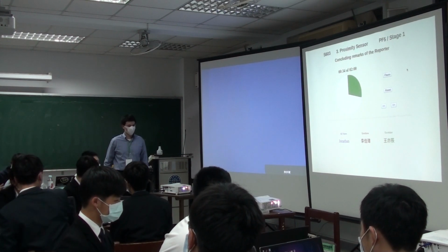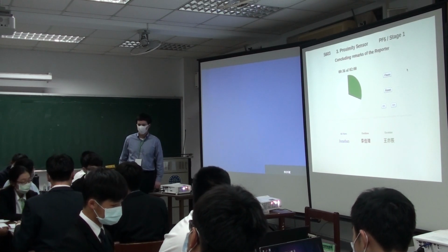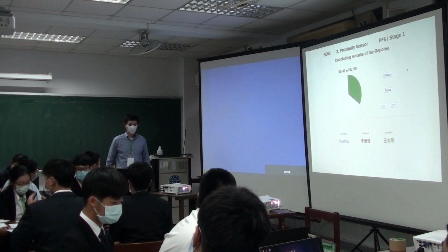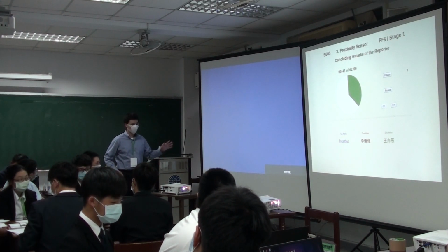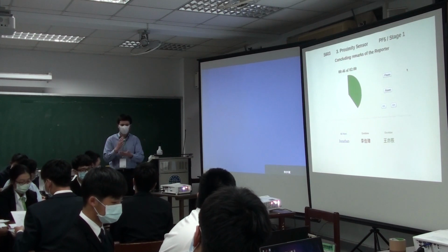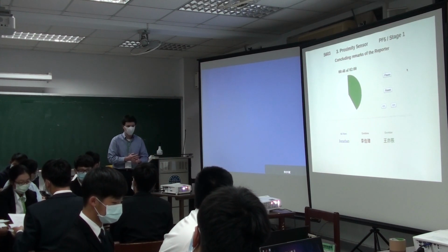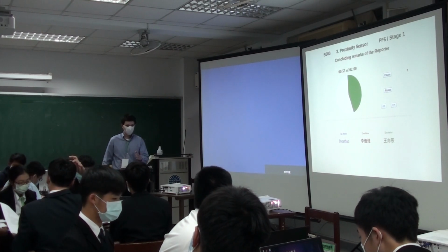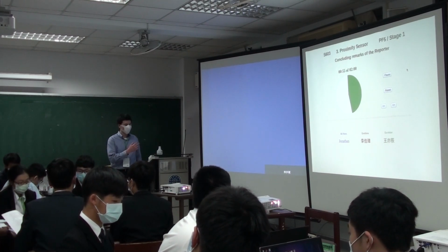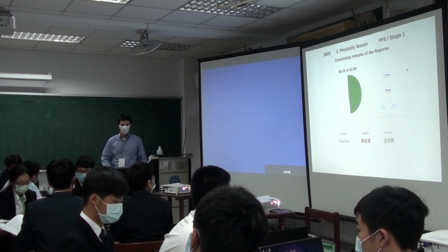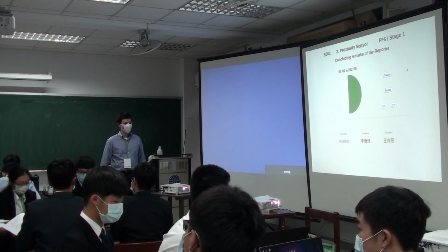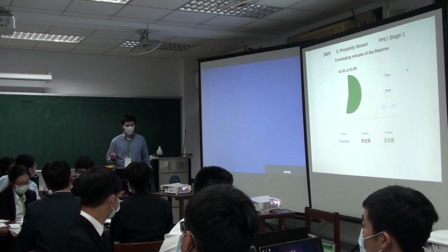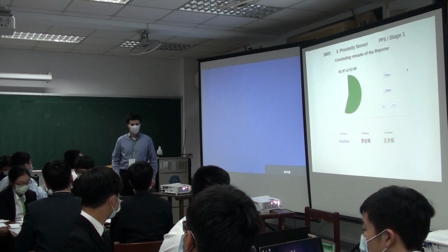In addition, there was some concern over the motion of the ferromagnetic material as it was passing through the coil, and we stand by our assumption that we can use our equations and measure point by point using our very high sampling rate oscilloscope in order to determine this. We do acknowledge that there is going to be some inaccuracy here due to Faraday's law, but we observed in our observational trials using a moving ferromagnetic material that this was not going to be very significant for us because the magnetization of the ferromagnetic material appears to be more significant in our own experiments.